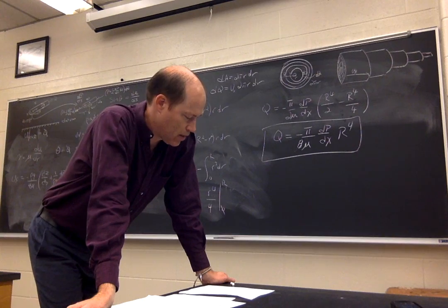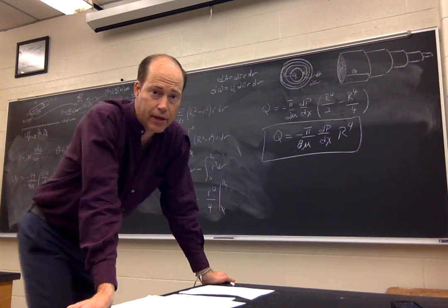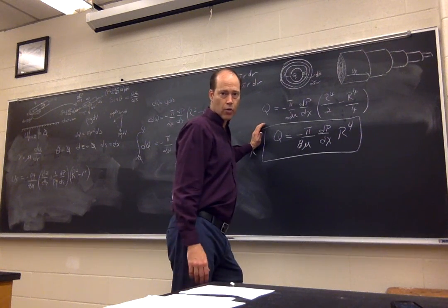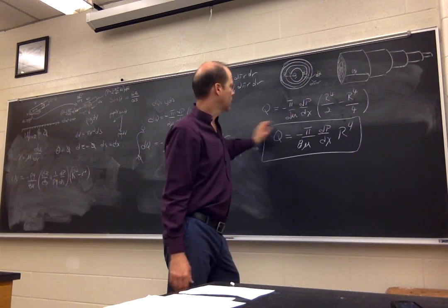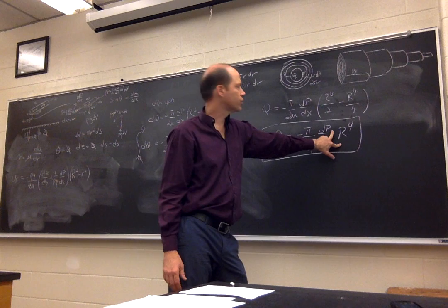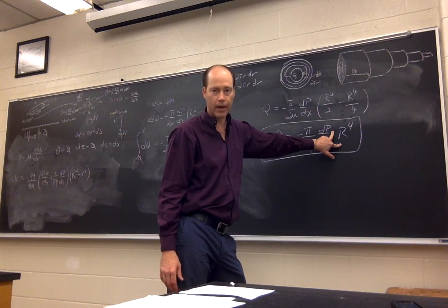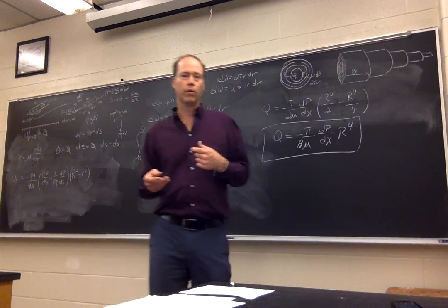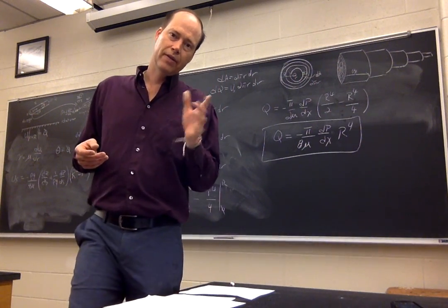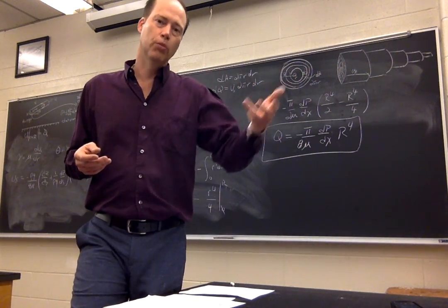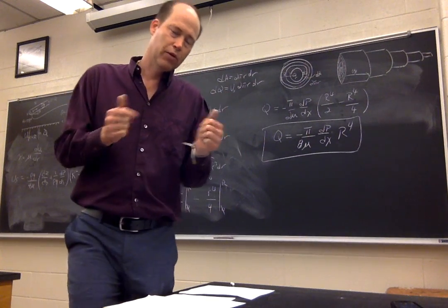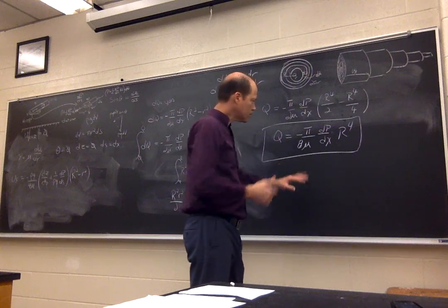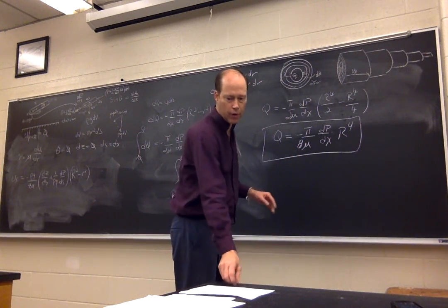So that is effectively Poiseuille's equation. By having a pipe, now the discharge is related to the radius of that pipe to the 4th power. In the cubic law, when we derived that, we saw that the discharge was related to the cube of the width of the pipe, or the width of the crack. So now we have the 4th power. This was done in horizontal flow.